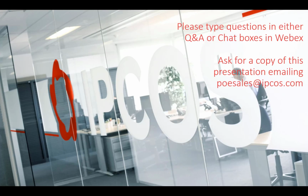The thing is, remember, PID controls run every second, half a second, whatever. And if you have an analyzer that is giving you a new signal every 5 minutes, well, you need to start thinking about it. If you have big dead times, because sometimes analyzers have transport lag times or whatever it is, those dead times also make it very complicated to try and configure such a control.